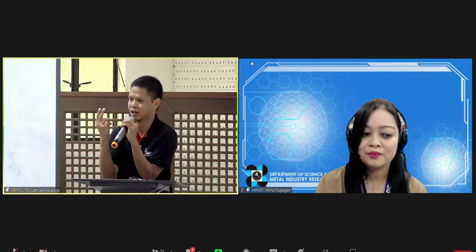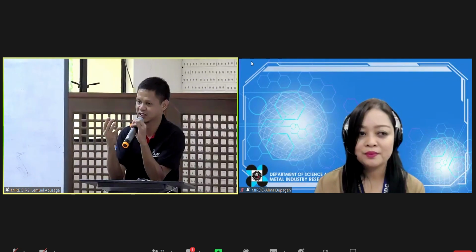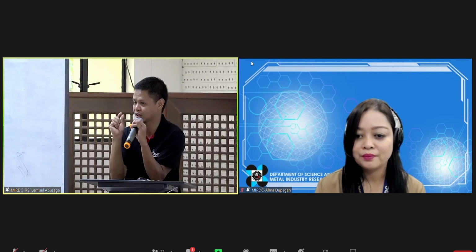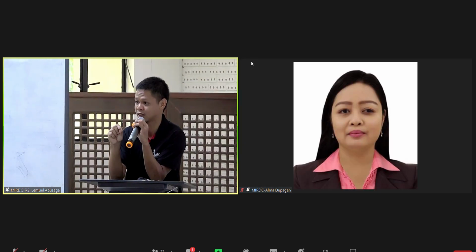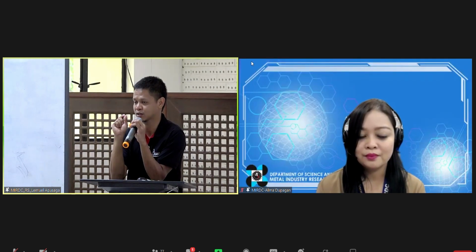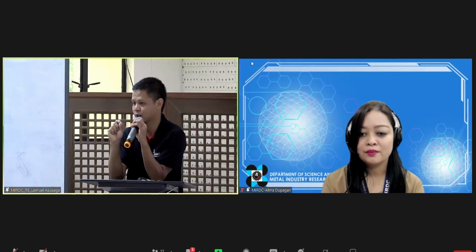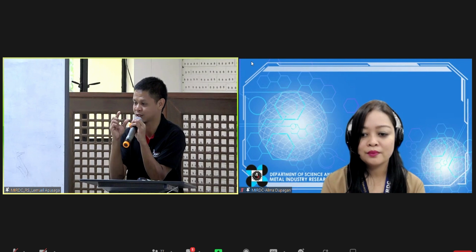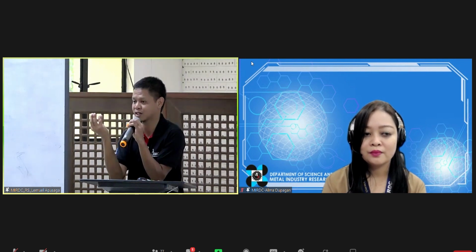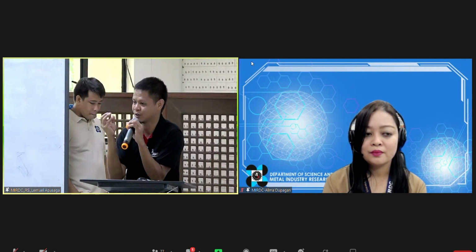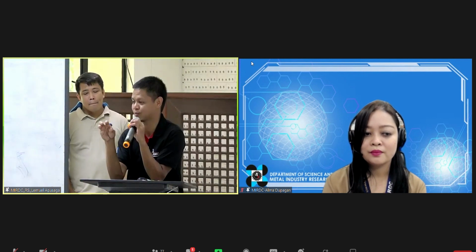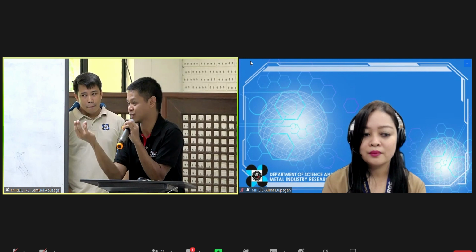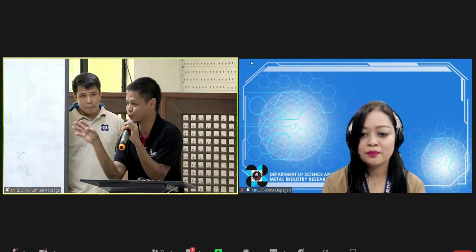The type of printer, I assume it means the type of technology, significantly affects the quality of the part. There are printers like the FFF printer, which is one of the cheapest ways to do 3D printing. It's going to make strong parts. At the same time, it's going to make very accurate parts, but up to some extent, it stops being very accurate when it comes to smaller parts. There are also printers that are able to make very, very precise parts, but with a different technology, like SLA. You start with a liquid resin, and light solidifies the part, and you end up with very, very precise parts. The limitation of those kinds of printer is the mechanical strength. It's not going to last long. So you have to choose which you want to make.